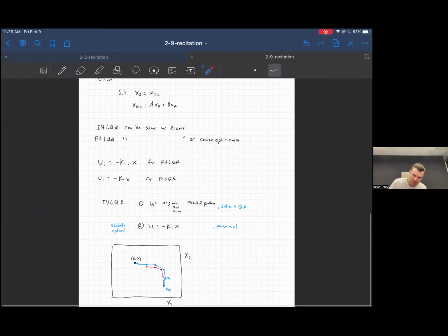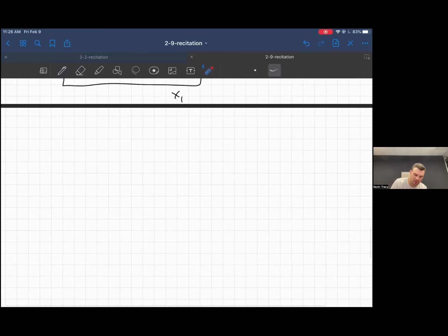So now the next thing we're going to talk about is using LQR to drive us to goals. In everything we've written so far, our cost function has been: minimize this thing with respect to the quadratic cost that just puts a penalty on everything. So it's going to drive the system to x0, u0. That's really where it wants to be. It wants to be at a point where nothing's happening. And that is not always possible.